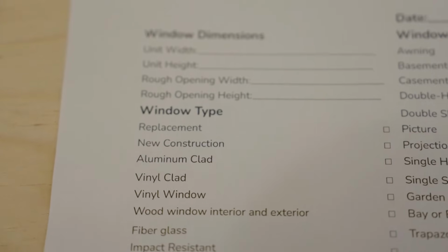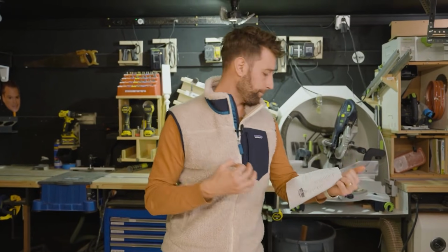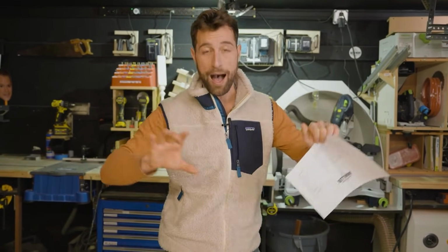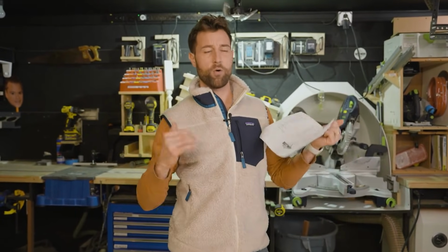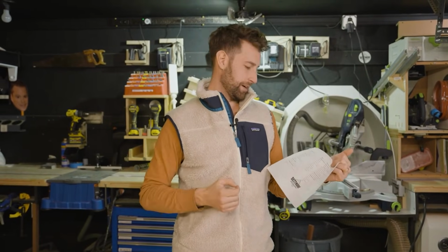What type of window is it? Is it a replacement window? Is it a new construction window? A new construction window is typically going in a new house, maybe it has a nailing flange and you're penetrating through that flange into the framing, and that's what's holding the window in, whereas a replacement window is basically going into the pocket of where you had typically old weight and chain windows. So it's going inside of that, and it's filling this wooden opening that was existing.